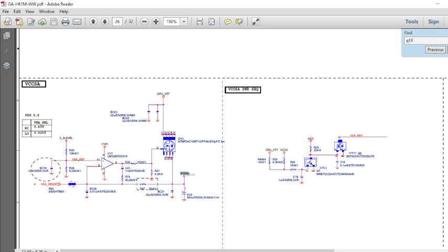And this is the output. This MOSFET, on the left side of our CPU socket, is MOSFET number Q13, which will have 0.95 volt. As you can see, it should be between 0.85 and 0.925 volt on this pin. Okay, this is again an important voltage.